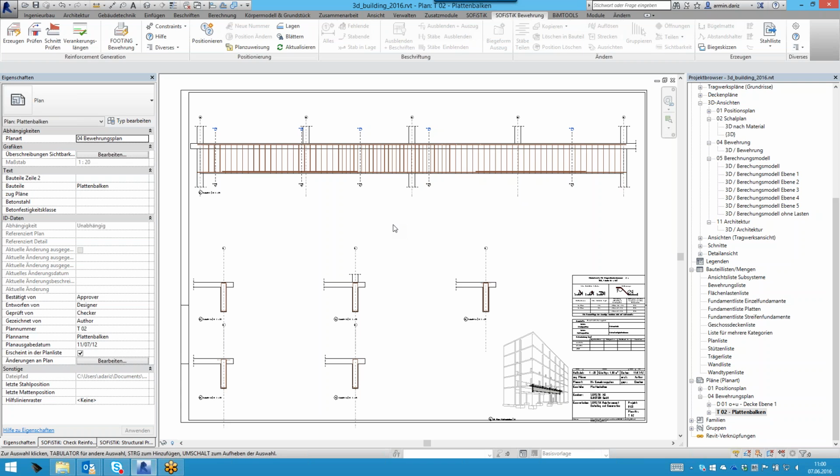If you have a different sheet, you can have the same bar number in that sheet with a different geometry from the first sheet. Therefore we have to assign all the rebars to a certain sheet.